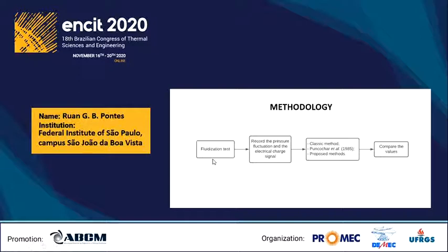Initially, the superficial gas velocity was increased from 0 to 1.716 meters per second, generating 45 points for the increasing test. After, the velocity was decreased from the point with velocity equal to 0.306 meters per second up to 0, generating 29 points for the decreasing test. These points will be important for the application of the traditional method.